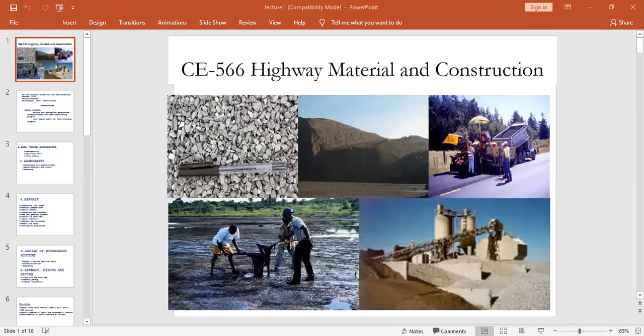We do have a longitudinal joint in an asphalt concrete pavement because we lay with lanes and lanes. Normally the paver can lay around 12 feet at a time. A traffic lane is 12 feet. So if you construct a 2-lane road, 12 feet and 12 feet, then obviously you will have a longitudinal joint between the two lanes. First you do the first lane, then you go for the second lane. So then there will be a construction joint. Now that is also being taken care of.